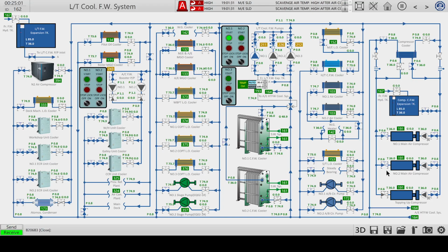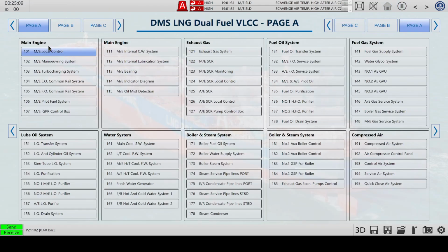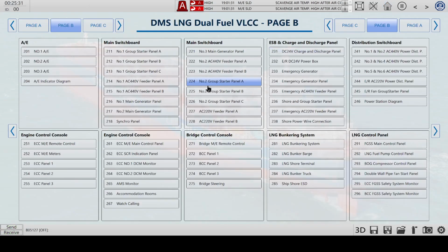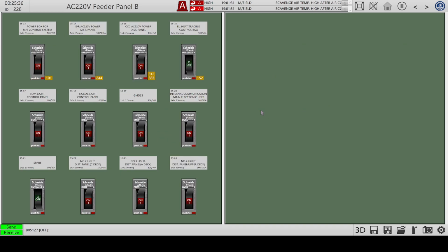Let's also set up cooling to our main air compressors, because that's the next thing that we're going to start. And just verify the diesel generator. We do have freshwater cooling. The target temperature is 90 degrees, so that's okay. Let's continue checking the breakers and close the ones that we're going to need.